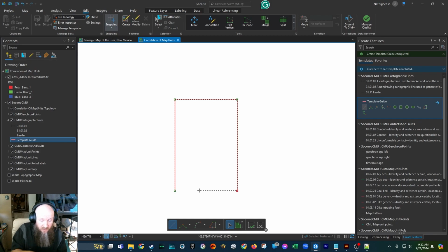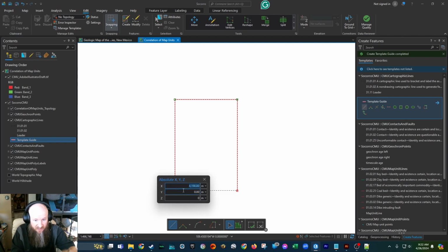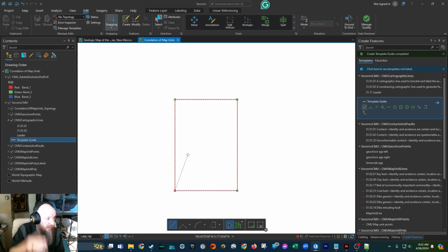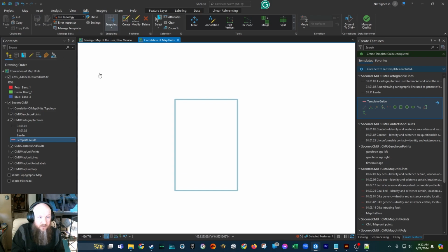There's a couple of different ways that we can do this. So again, I'm going to show the directional method. I want to go 270, lock it in. I can then come over here and snap to, and I can double click and do all those things. But again, I want to hit the F6 key so that we can see we want to go to X at 0 because we're going back to 0, 0. And when I hit that, I get back at 0, 0. I hit F2 to finish my sketch, and now I have my neat line. I'm going to save those edits. I'm going to clear my selection. So now I've got a neat line that I can georeference to.